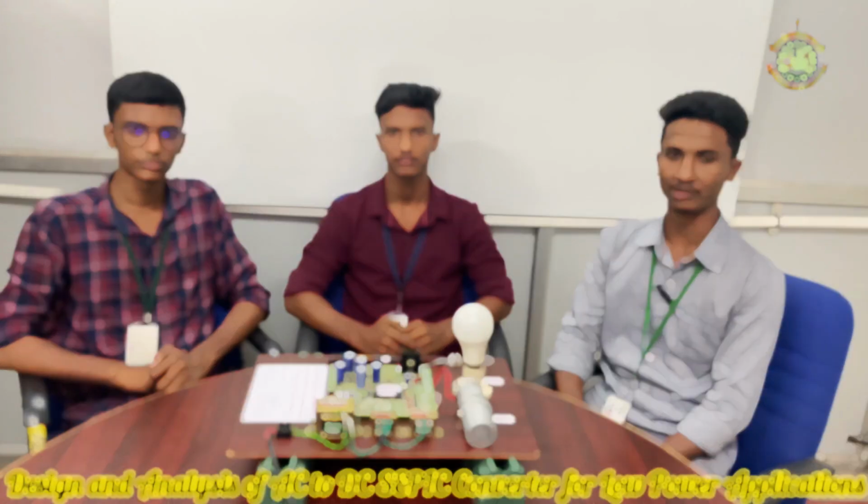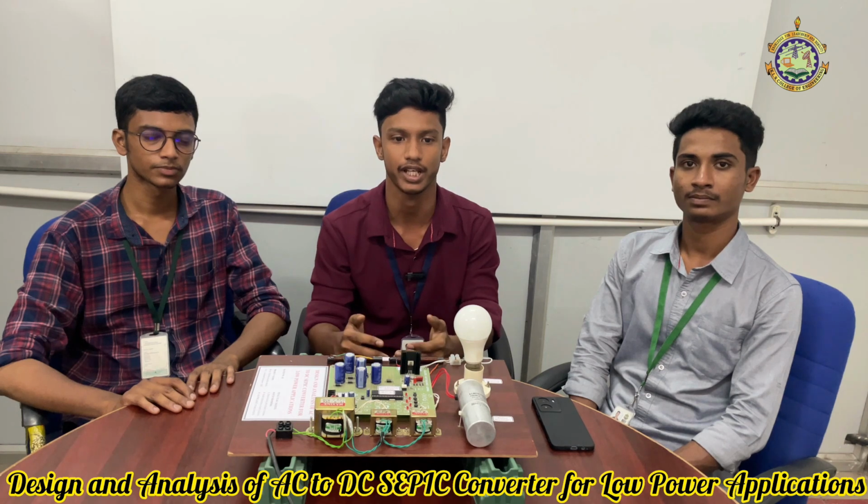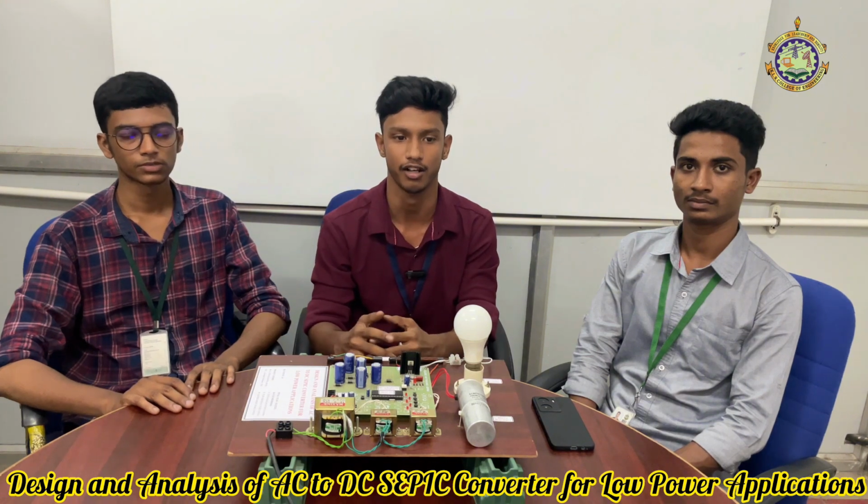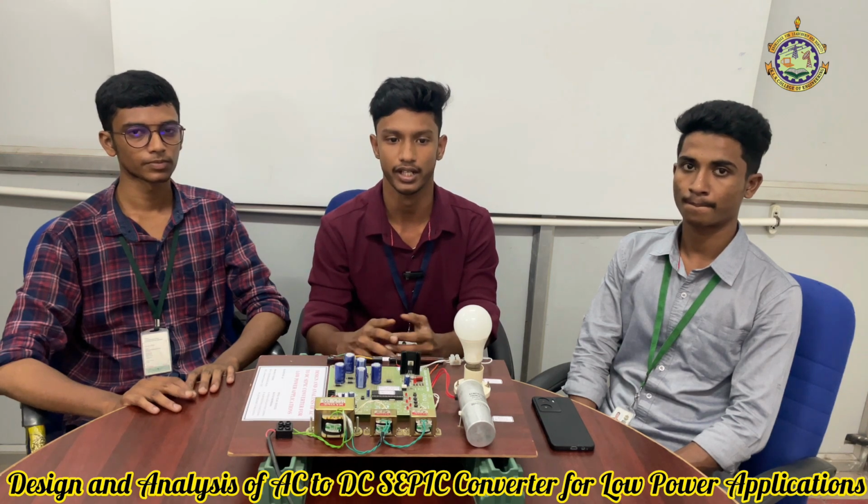at 1 ampere. The SEPIC, or single-ended primary inductor converter, is a non-isolated DC to DC converter that can step up or step down voltage with a continuous input current, making it excellent for reducing EMI, that is electromagnetic interference, and harmonics. And the components we have used are two inductors, L1 and L2, for energy storing and transferring,